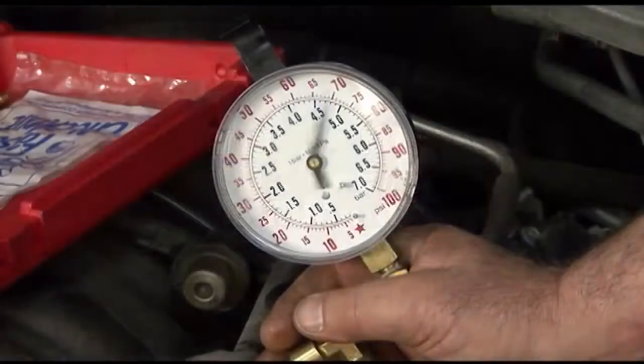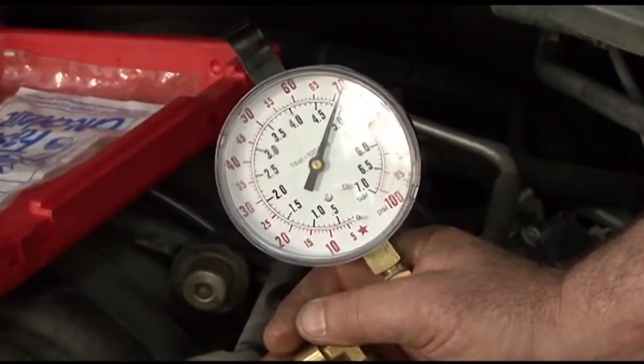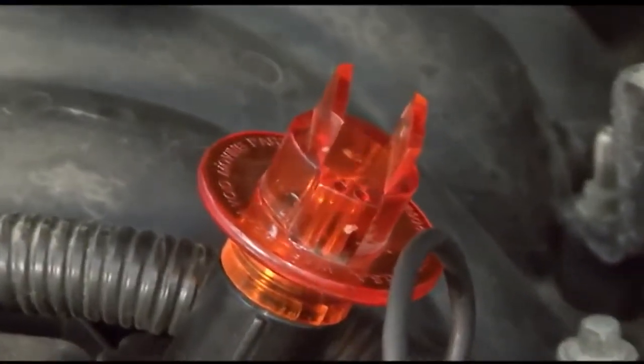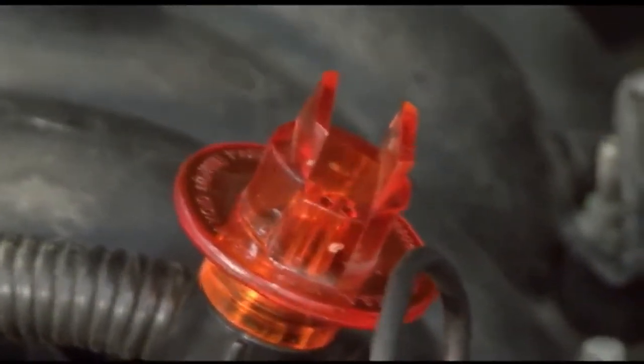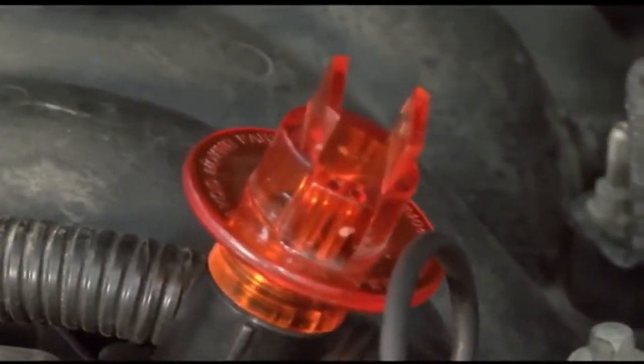Begin by checking both the static and running fuel pressure and compare them to published specifications. This is a noid light. When hooked up in place of the injector, it will tell you if the powertrain control module is sending a signal to fire the injector. Some techs learn the hard way that a noid light might show you that the computer can try and command